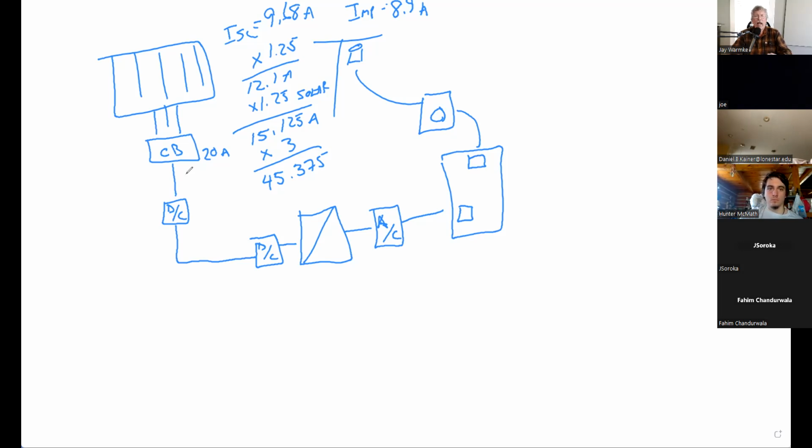And the reason for that is the ampacity rating of your wire is not just the ampacity rating of the wire, but it involves the connection points of each piece of equipment on both ends of that wire. So I'm connecting into a combiner box, and in this case, I'm connecting to a DC disconnect. Well, each of those connection lugs that you're going to hook into has its own temperature rating. You know, is it rated for 60 degrees Celsius, which is what that first column is? Or is it rated for 75? Or is it rated for 90?